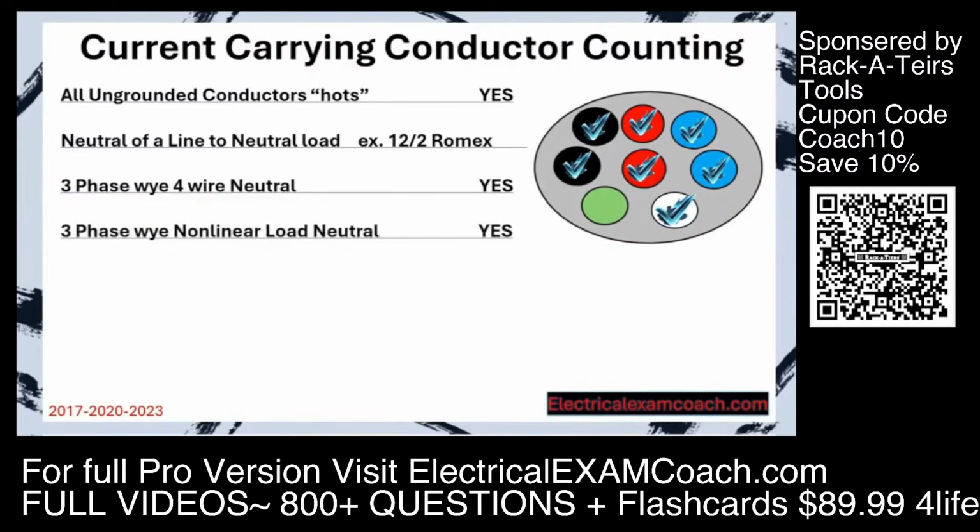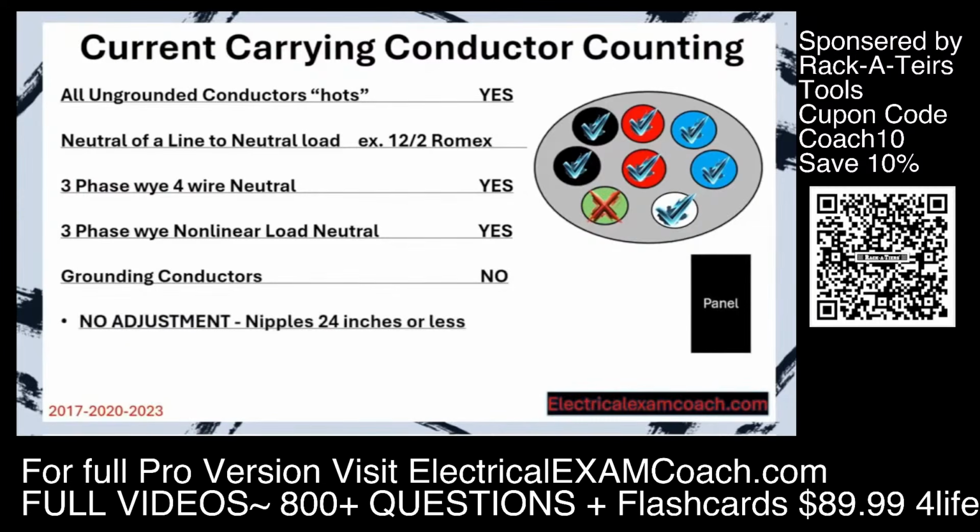Then the 3-phase nonlinear neutral load. Nonlinear loads come from large fluorescent lighting or from large computer data centers. You're going to count its neutral as well. Grounding conductors, no, they do not count, and that's one of the easiest ones. You don't have to count those as a current carrying conductor. No adjustment will be made if we have nipples that are 24 inches or less. Let's imagine we have a panel over here on the right-hand side. We put a panel on the left side. We want to run a short nipple that's 24 inches or less. This does not count in our bundling adjustment.